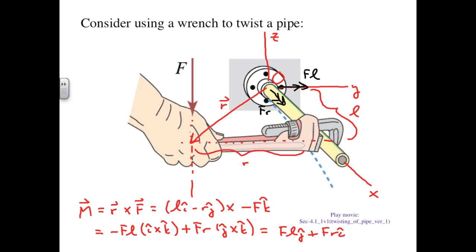If the rotation is parallel to a long axis intended to admit rotation, the moment is a torque or twisting moment. If the rotation is perpendicular to an axis intended to admit rotation, the moment is a bending moment. In the present illustration, the F_R component along I is a torque, and the F_L component along J is a bending moment. If we wanted to loosen the pipe more easily while minimizing the bending, we could simultaneously increase F, use a longer wrench, which would increase R, and grip the pipe closer to O, which would minimize L.